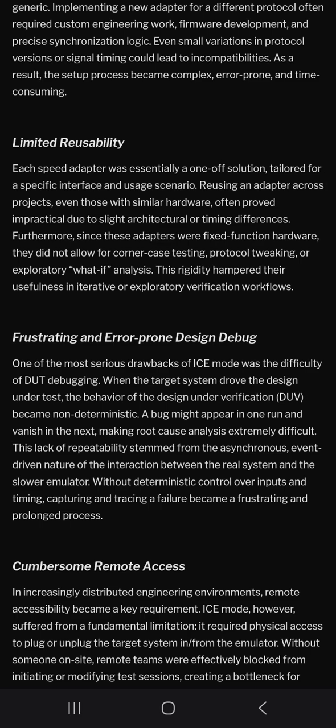Frustrating and error-prone design debug. One of the most serious drawbacks of ICE mode was the difficulty of DUT debugging. When the target system drove the design under test, the behavior of the design under verification became non-deterministic. A bug might appear in one run and vanish in the next, making root cause analysis extremely difficult.